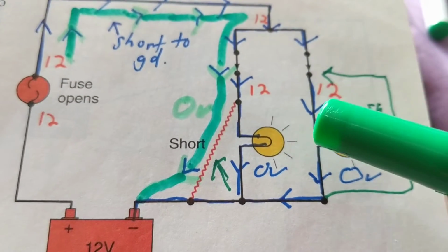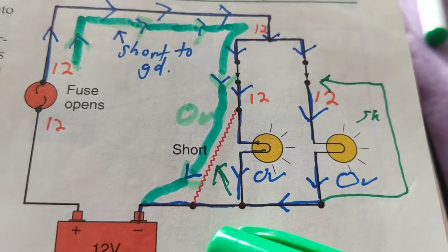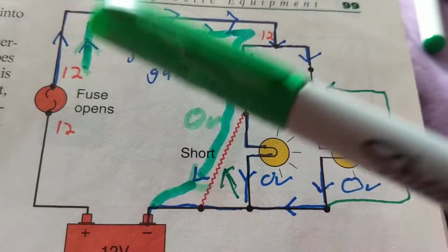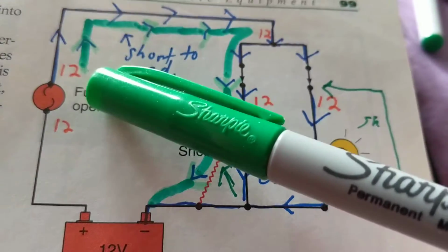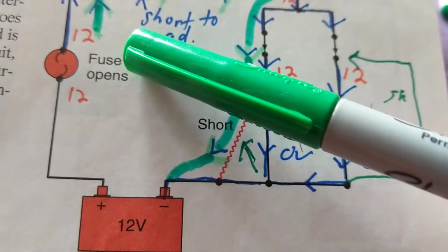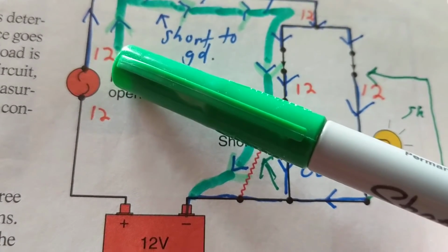Now, guess what? Same result. We have a short to ground. It'll pop again until we find the one where the short is. So putting in another fuse, no, it's costly. Maybe it's not that costly because they're so cheap, but it's not troubleshooting.